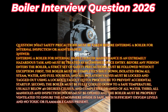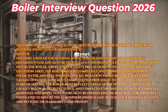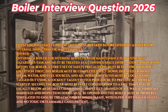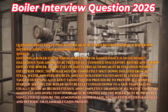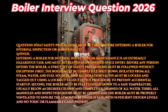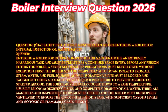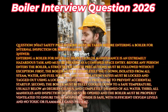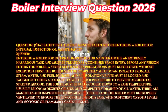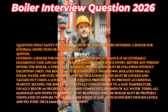Answer: entering a boiler for internal inspection or maintenance is an extremely hazardous task and must be treated as a confined space entry. Before any person enters the boiler, a strict set of safety precautions must be followed without exception. First, the boiler must be completely shut down, isolated from all steam, water, and fuel sources, and all isolation valves must be locked and tagged out using a lockout-tagout (LOTO) procedure to prevent accidental startup.